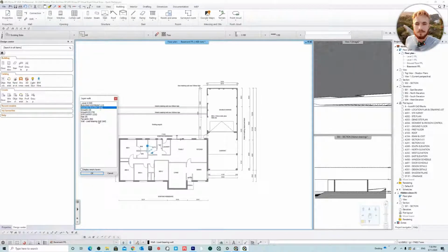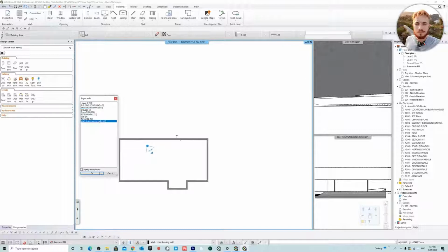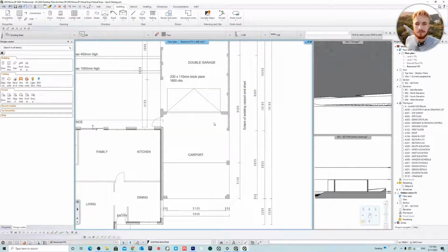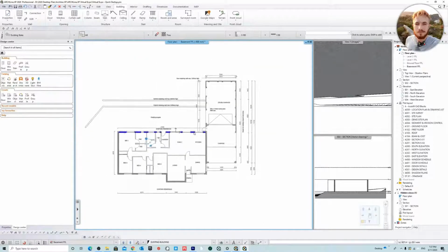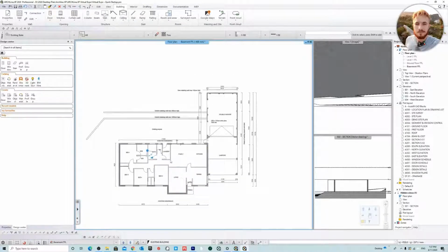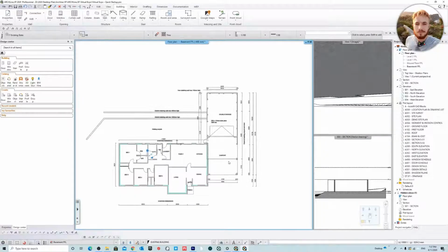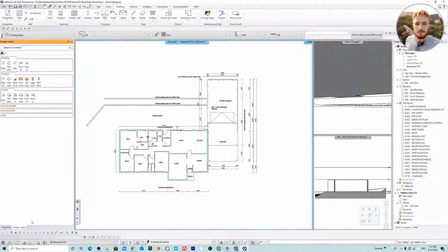I think I'll stick with load-bearing walls. But I'll show you the other way around as well. So we'll go existing building. Okay, now you can actually change the color appearance of this, and you can make it lighter. So let me show you how to do that, because this is essentially a ghost layer. Okay, so if we go down here to settings, how to display visible but inactive levels. Okay, replacement color, you can do halftone, right? And it's going to show like this.